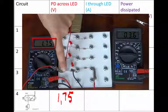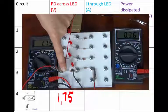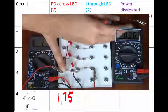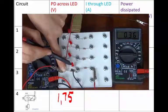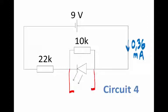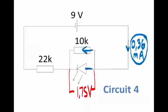1,75 volts. Now we have to be careful. We are measuring 0,36 milliamperes, but that is through the main part of the circuit here. It's not through the branch, the LED. So we have 0,36 milliamperes flowing in the main part of the circuit. And we know that across these components, across the parallel connection, we have 1,75 volts. So from that we can calculate what the current strength is through the 10K resistor and subtract that from the current through the main part of the circuit, because the remainder goes through the LED.